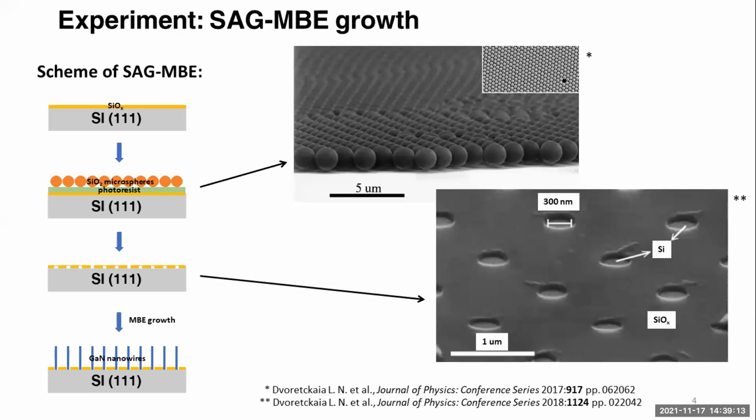On this slide, you can see the difference between the classical growth of nanowires and selective area growth, which uses a substrate pre-coated with an inhibitor layer with ordered holes with defined density, location, and size. The figure on the left illustrates the main stages of selective area growth.